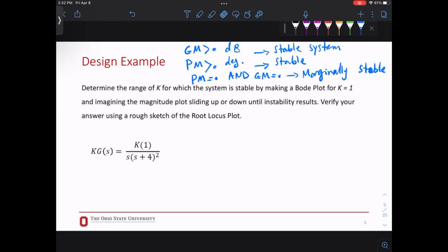So there is one integrator in the system, or the power of S is 1, which relates to one integrator in the system. That's how we define system type. That's why we use a PI control to make the system type 1 if it is not, or add 1 to the type of the system, right? So make sure you connect what you learn and repeat it, because it helps you get intuition when you're designing your controller. All right, so this is system type 1.